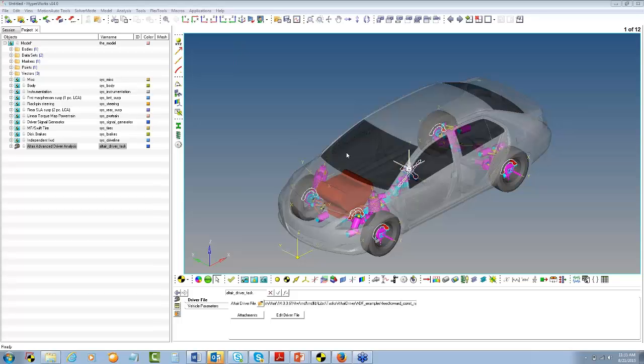Is there any difference if we mount springs to the lower or upper wishbone in anti-squat or anti-drag? Of course, there are some differences, but they are generally more related to which control arm is getting the load and its bending properties, and it should not matter much with anti-squat and anti-drag. ABF and PLT are both kind of result files. The difference between them is one is binary and one is ASCII, so it should not matter to you. I think the only difference is the size. So if you want to port it to someone, better to port an ABF file because that is smaller in size.